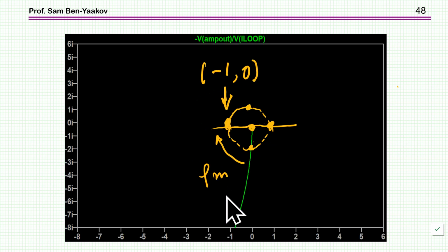And in fact here I'm zooming in, and this is now the 0 point, so this is -1, 0, and for the circuit to be stable you have to avoid encircling this point, and we are not. In fact, we are penetrating this unity circle at 90 degrees, which is consistent with the phase margin of 90, which we have seen in the Bode plot. So everything is consistent here, but the operation is kind of questionable because of this reactive and oscillatory behavior.